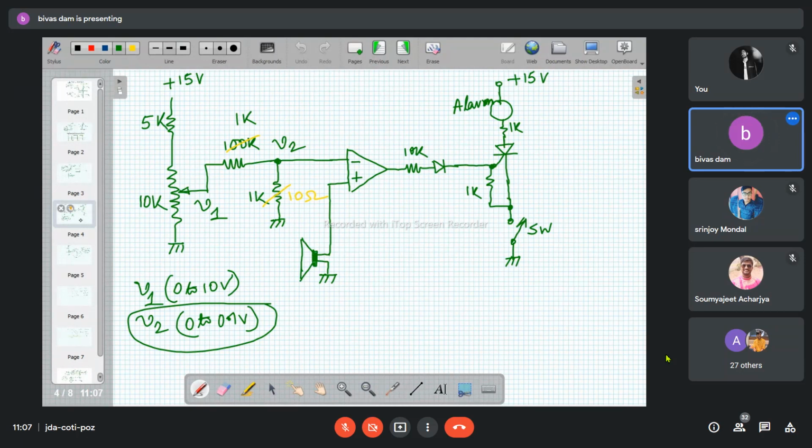So that in that operating frequency, the capacitance becomes dominant over the resistance. There is a very wide concept of rule of thumb in electronic design, and in that rule of thumb, anything multiplied by 10 is supposed to be much higher than the other one.